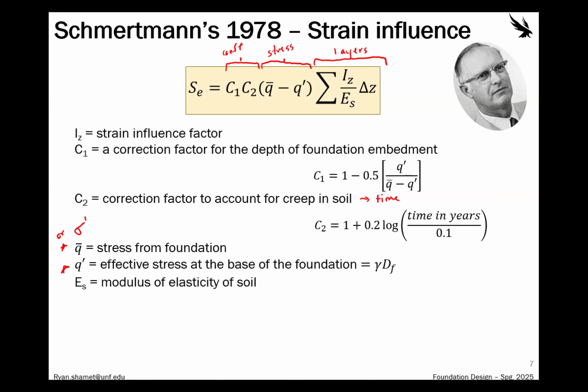So this is still an elastic settlement. So you can still see the soil property that we care about is the modulus of elasticity of soil. But you'll see there are good correlations to subsurface testing for this modulus of elasticity, which helps us get an understanding of the modulus of elasticity and how it changes with depth. So we can do a standard penetration test, or we can do a cone penetration test, and we can correlate that testing data, which is a resistance value per depth of penetration or depth of soil. We can get that and then correlate it to Es.